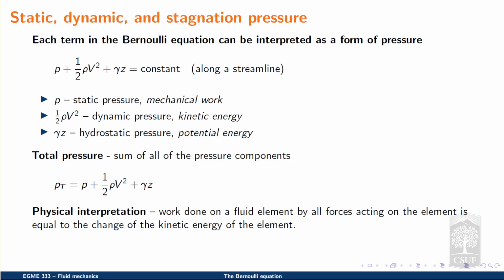A physical interpretation of the Bernoulli equation is that the work done on a fluid element by all forces, whether they be pressure forces or gravitational forces, the sum of those forces is equal to the change of kinetic energy of that fluid element.